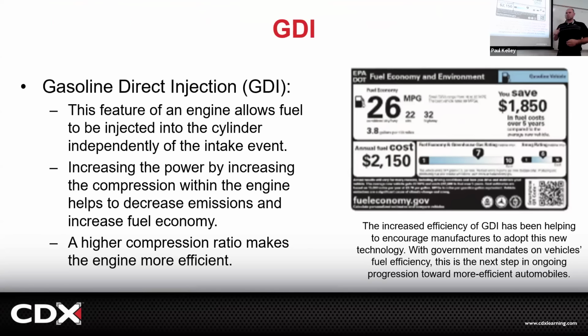The evolution of the fuel systems shows carburetor, throttle body injected, port fuel injected, which was good for a long time, but port fuel injected's out. Gasoline direct injection gives us better fuel economy and lower emissions. It costs more money to manufacture. You get to pay the cost on that. We need to hit our CAFE, our corporate average fuel economy, and we need to hit our emission standards. Government said so, so you're paying for it now. You don't have a choice.